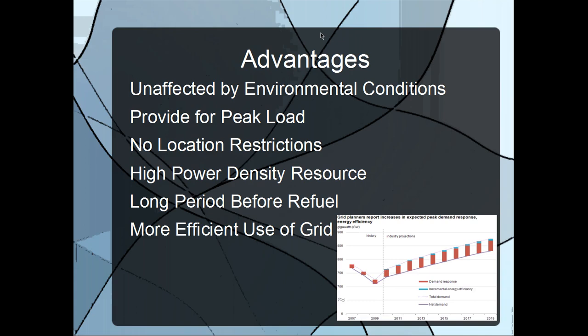The inability of these renewable technologies to maintain a constant output also prevents supplying for peak load. When need is placed on the grid, a readily available source of power must be online for immediate consumption. Availability depends completely on environmental conditions, an independent variable that will always plague these options. This characteristic forces solar and wind to play a supporting role behind 24-hour available sources such as nuclear.